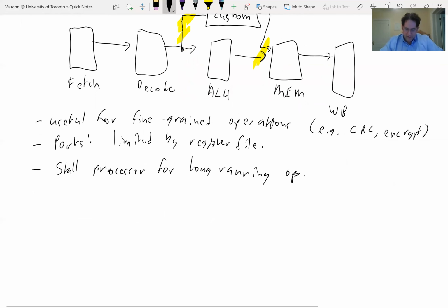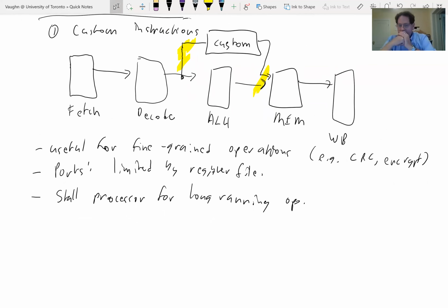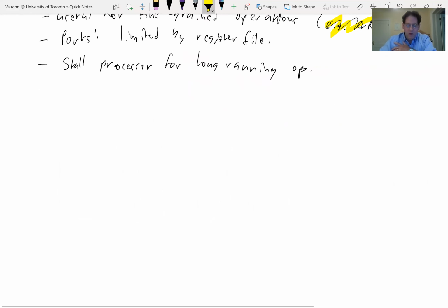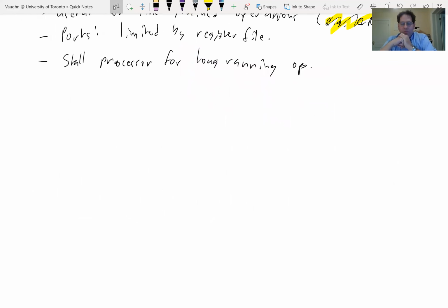So this is kind of a cool idea, and it's had some success, as I said, in this limited domain, primarily in CRC and encryption. One of the challenges you always have when you're programmable is if it's too good an idea, then it might get copied by fixed devices. So some hard processors now have instructions in them that make them better at CRC and encryption. So if everybody wants the same custom instruction, or many people do, then the regular processor vendors will actually eventually put that in the instruction set.